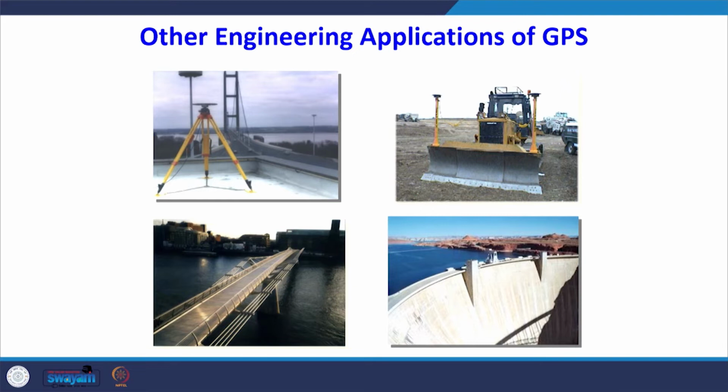Here you are getting the latitude, longitude and altitude of the point where you are standing with this GPS device. You should have a clear visibility to the sky; that is the only condition when you are using this instrument. If we look at the applications, whether it is road construction, putting on a dozer, digging the earth, monitoring bridge deflection, doing alignment surveys, or monitoring dams where cracks are developing or deformation is taking place.